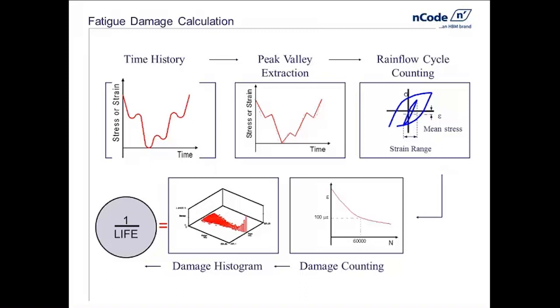If the time history I was bringing in was a single cycle, this scale factor would be identical to a constant R ratio factor of safety. One difference between the stress-based and life-based calculations: the stress-based is giving you a factor of safety solely on the worst cycle. The life-based is giving you a factor of safety on the entire damage, the damage created by the entire time history.